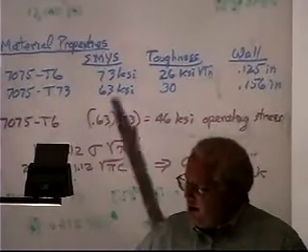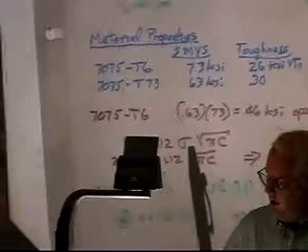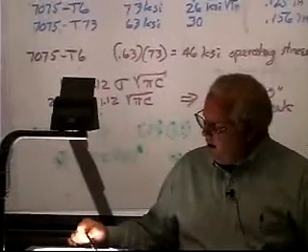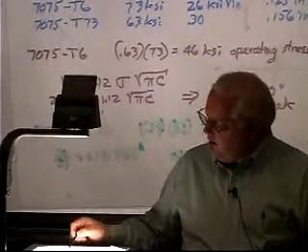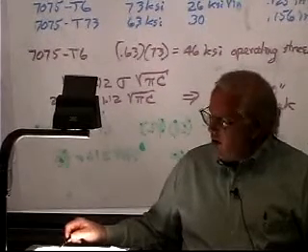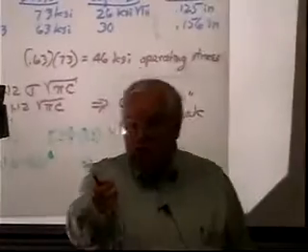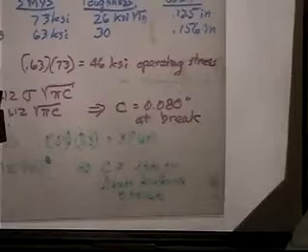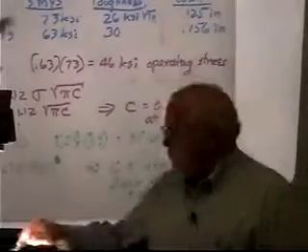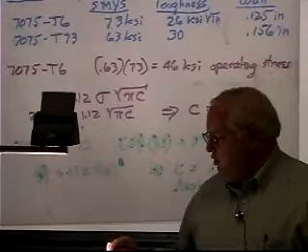And it turns out by doing that, if you go through the stress intensity calculation down here, you'll find that the critical flaw size to break in the original design is about 2mm. You look at that thing, that crack goes about 2mm down. We just verified that these material properties I looked up in a handbook for the original 7075 T6 are correct.